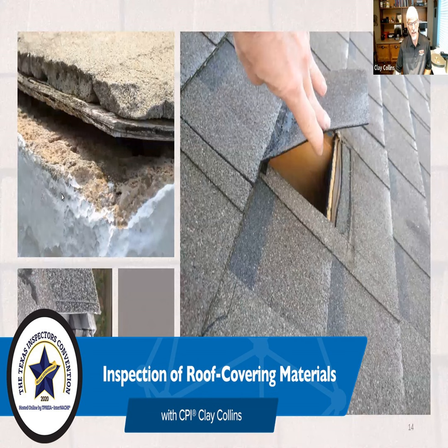Granule loss. This looks like a manufacturing defect. You can see that there's a very distinct pattern, and that is a separate issue, but that to me is not abrasion or wind or anything else. The installer never should have allowed that to stand. The builder should never have allowed that to stand.